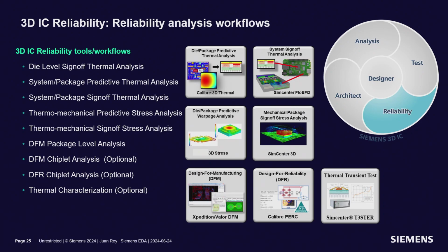Now, the issue doesn't end there. You need to also be able to support design for manufacturability issues that have been pervasive already in the industry at the PCB level, at the package level, at the IC level. You need to focus also on design for reliability issues, electrical rule check problems, such as electrostatic discharge checks, but now you need to do that type of analysis, again, for each one of the chiplets in the whole context